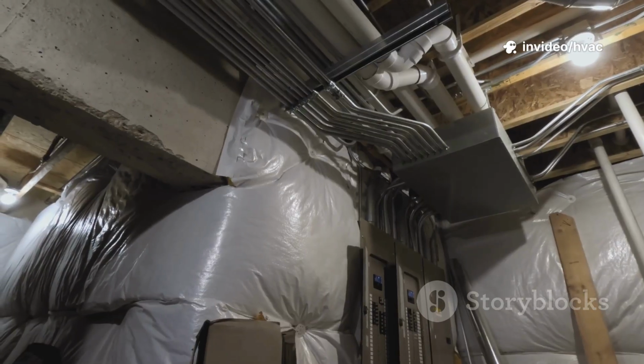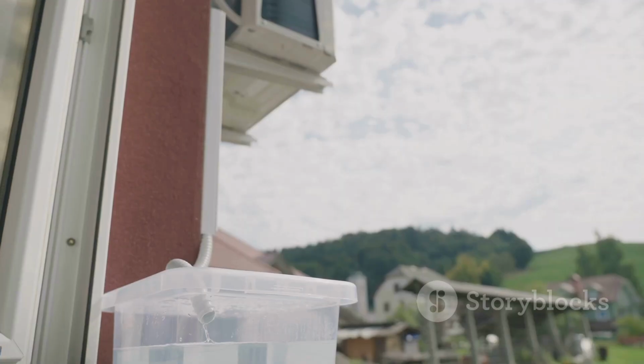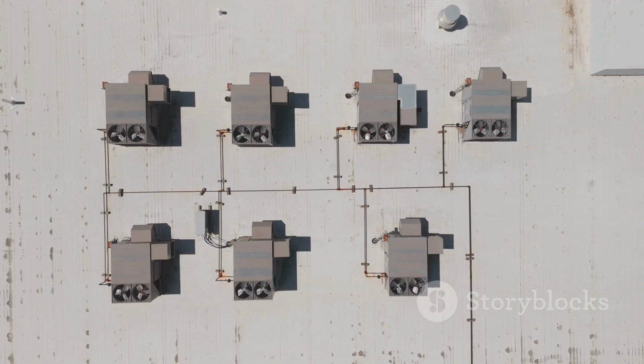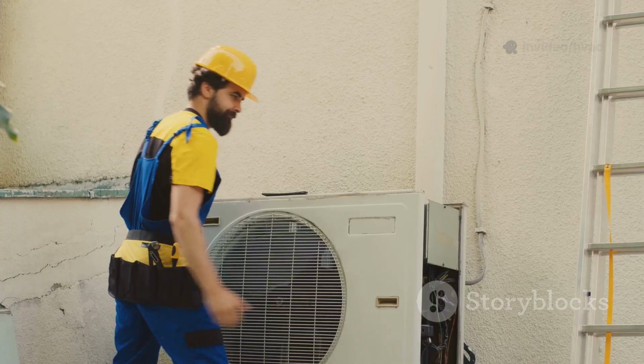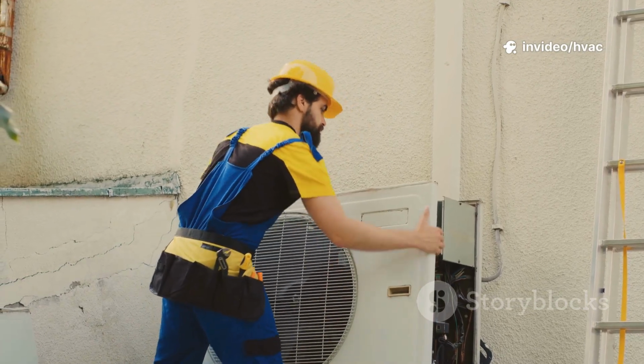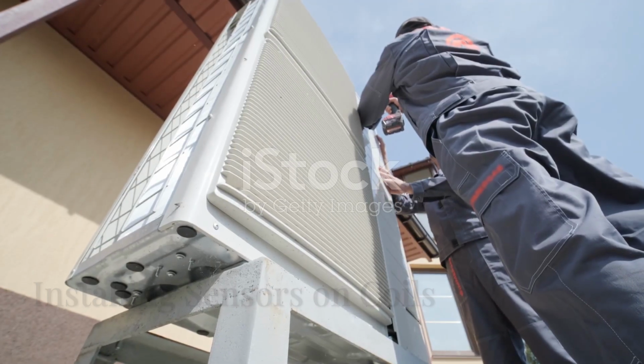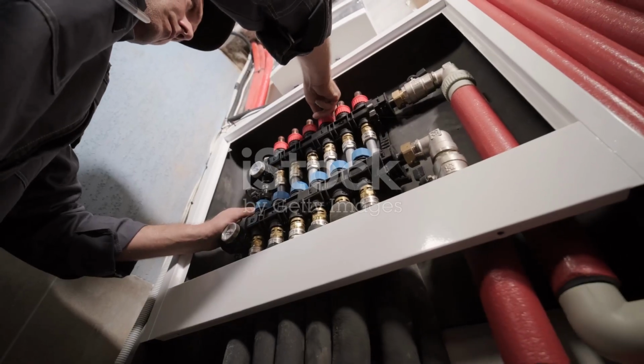Always install the sensor on the downstream side, the air leaving the coil. This is where freezing or overheating is most likely. Cover the entire face for safety and efficiency. Next, let's see how to install these sensors for best results. Details matter here too. With the right sensor length, installation is all about coverage and care.